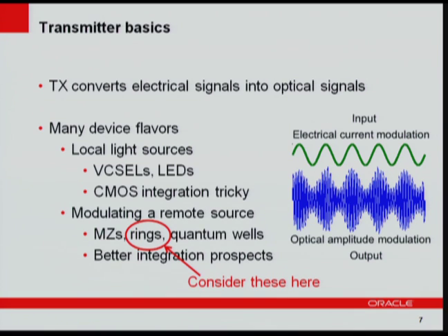As you heard from the previous talk, rings are resonant structures, meaning there are modes within that ring which resonate. As you vary, say, the path length by some electrical means, you change the resonance frequency, and the original source that you had then does not resonate and does not go into the ring.